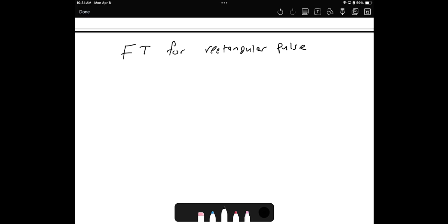And this is very common in real life, it looks like when you press a push button. When you press a push button, it will be on when you press it and hold it, and when you remove your finger, it will be off. So even if you press it quickly, it will last for a few milliseconds, right? You cannot do it as an impulse, as one signal at once. So when you press any push button, it will produce a pulse, called a rectangular pulse. So for the rectangular pulse, we will assume this event happens once. There is no one keep pressing. You just press it once, and we will see how this will affect.